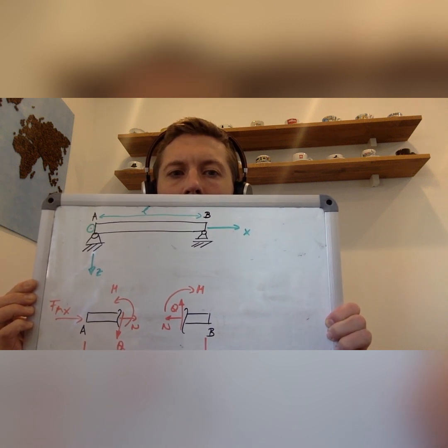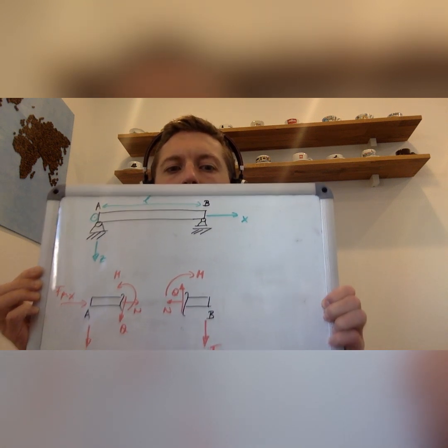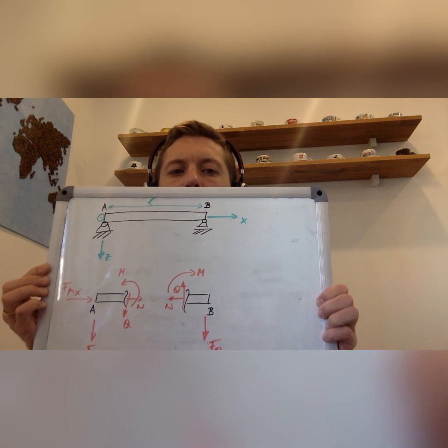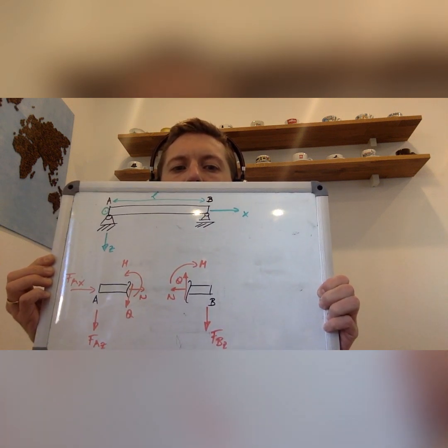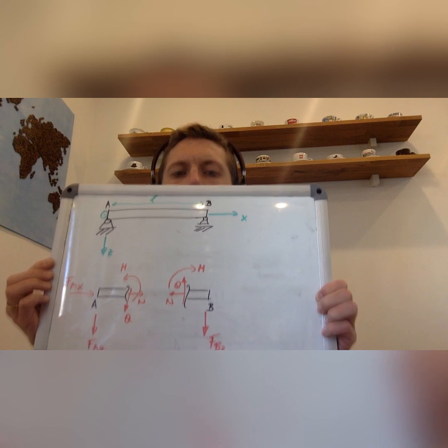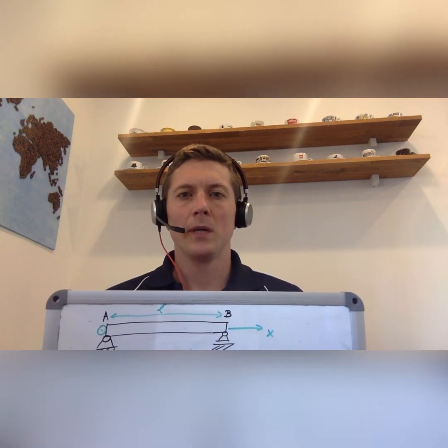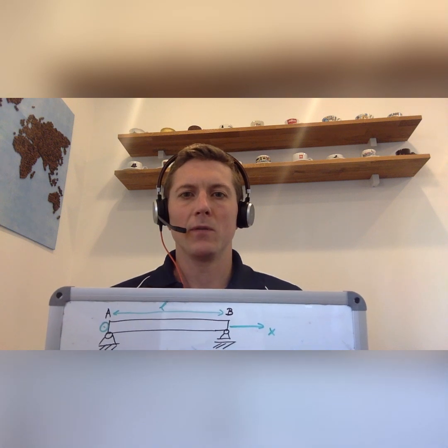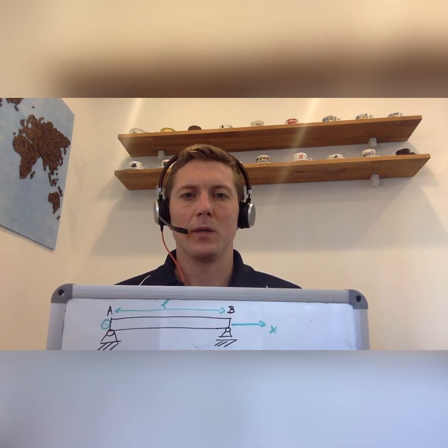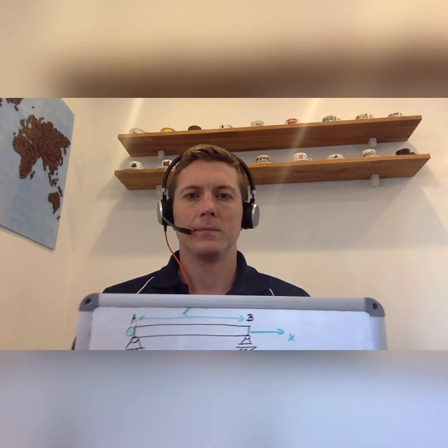One further hint for the free body diagram: if you apply the external bearing reactions, so in A and in B, you would add here two forces in z direction, FAZ and FBZ, as well as one force in x direction, FAX in this example. And as we do not know the bearing reactions in advance, I would strongly recommend to apply them in positive coordinate direction so that you can apply the formulas you have learned about in the lecture.